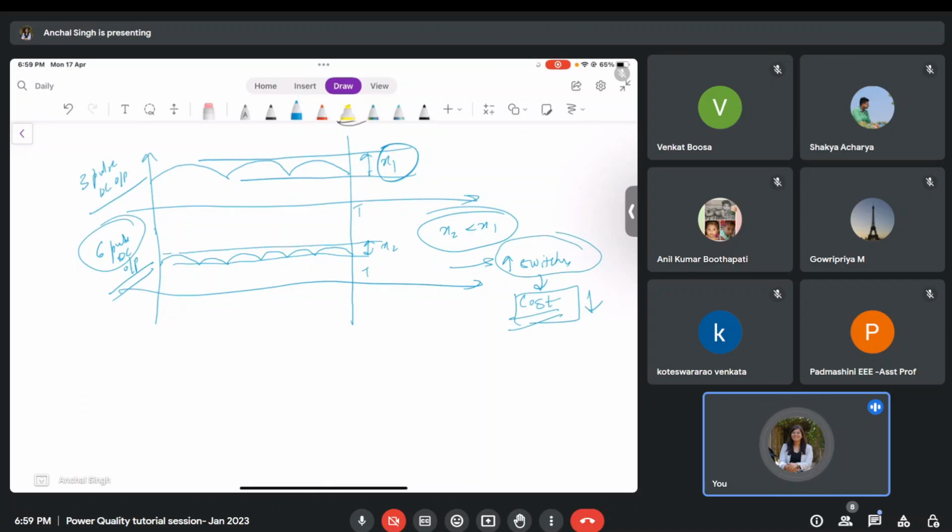Therefore, you can have power supplies available in the market from 30,000 to lakhs. There are power supplies which are available at 2 lakhs, 3 lakhs, and there are power supplies available for a few thousands. The parameter that varies amongst these power supplies is their accuracy or the ripple content. The costlier ones are closer to pure DC, and the cheaper ones have a lot of ripple inside them.